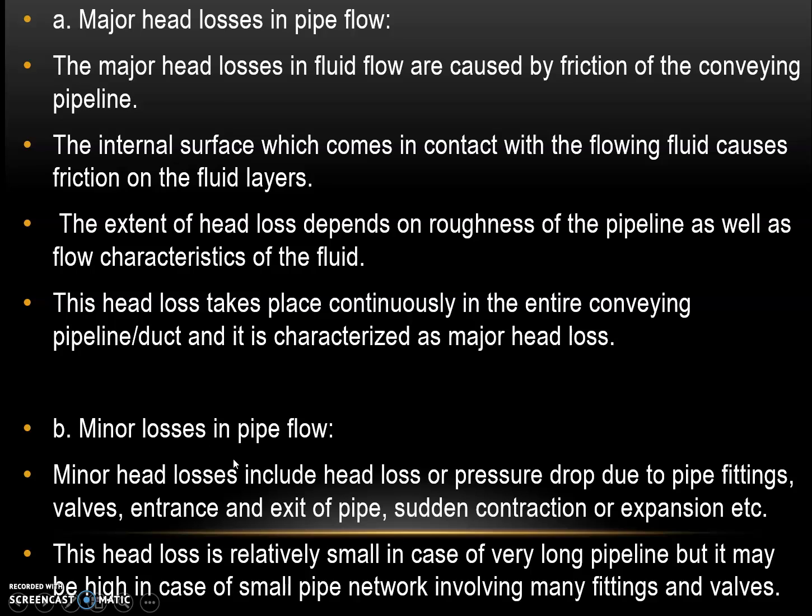Minor loss in pipe flow is the head loss or pressure drop due to pipe fittings, walls, entrance and exit of pipe, sudden contraction or expansion, etc. This head loss is small in case of very long pipeline, but it may be high in case of small pipe network which involve many fittings and valves.